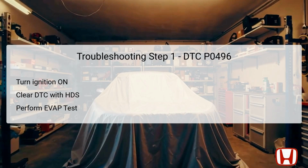The first step in troubleshooting DTC P0496 involves turning the ignition switch to the on position or pressing the engine start-stop button to enter the on mode. This will prepare the vehicle for diagnostics.